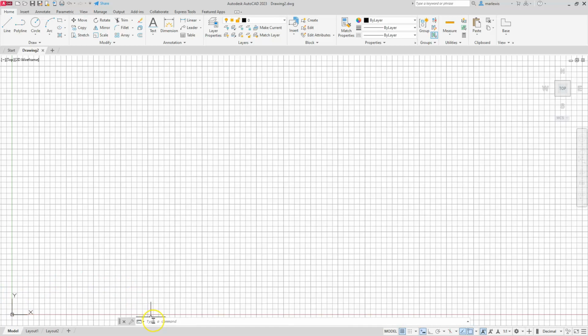The command line is going to be our super important thing. This is the way that AutoCAD interacts with us. A lot of times when I was teaching this class, or anytime I'm doing it in a live demo, I get a lot of comments from new students that said, how do I know when to hit enter? A lot of times when you see nothing is happening or after you invoke something, basically if I tell AutoCAD to start somewhere, it's asking me for that input back. So you have to tell AutoCAD when to go to the next step. Some commands will do that when it's satisfied and jump to the next one. But for the majority of it, if it's just sitting there looking at you, that's probably a good sign for you to go ahead and hit enter.